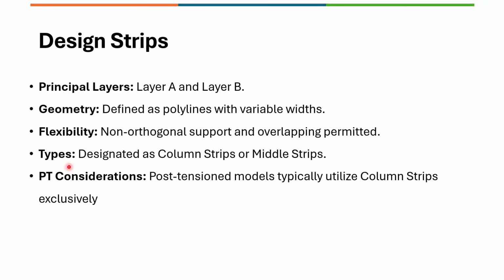So it need not be strictly orthogonal. It can be radial or other non-orthogonal directions because of the geometry of the slab. And these orthogonal or slightly non-orthogonal strips will be overlapped. That is totally fine.